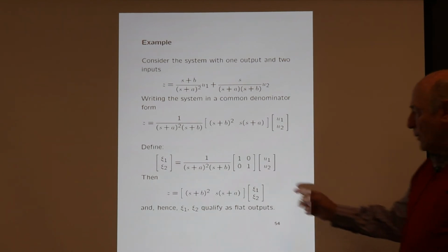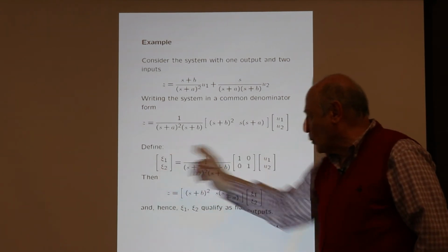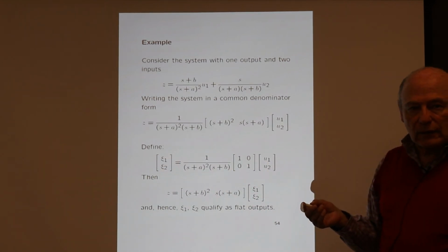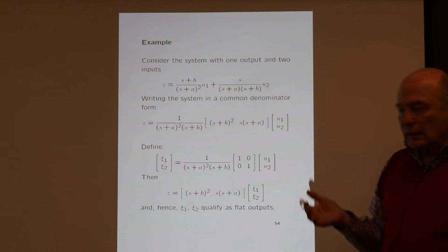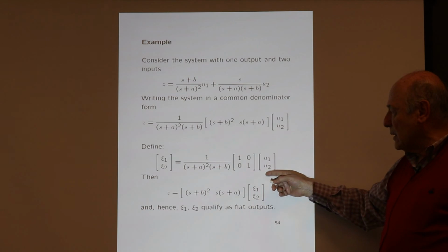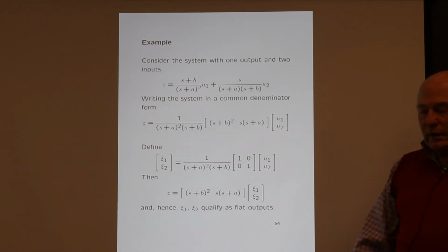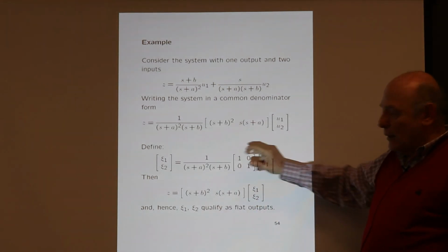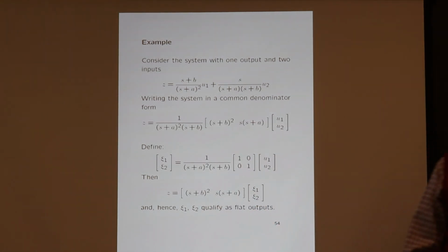So now we have that these two matrices are coprime. They don't have any common factor except the trivial factor, which is the identity matrix. That's trivial. So these are coprime. This has the dimension of this, and this matrix, because you can put always this matrix there. This matrix is unimodular.